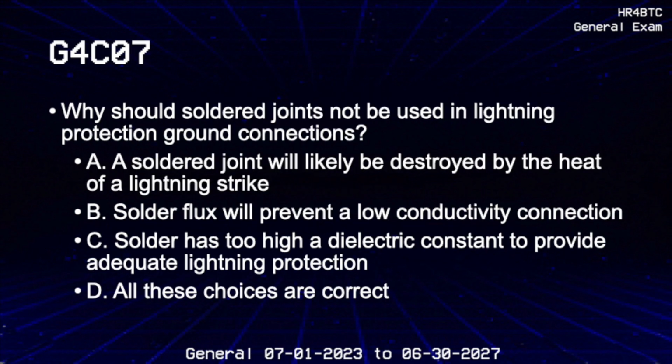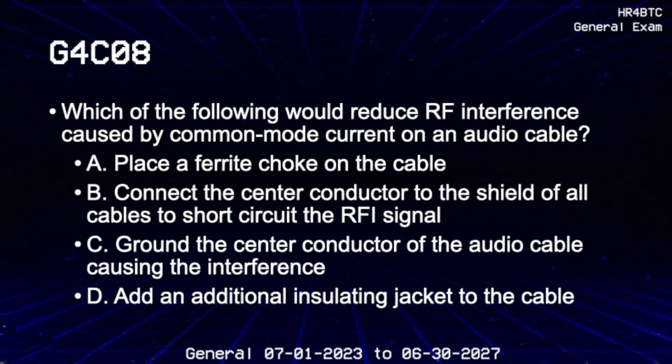Why should soldered joints not be used in lightning protection ground connections? A soldered joint will likely be destroyed by the heat of a lightning strike. Which of the following would reduce RF interference caused by common mode current on an audio cable? Place a ferrite choke on the cable.